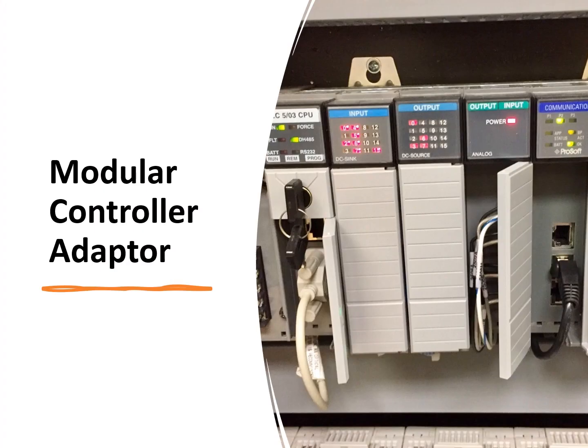Another modular adapter chassis shown in the figure below is the SLC 500 modular controller system. The configured controller system consists of the chassis itself, power supply, CPU module, SLC 503, an input module, an output module, an analog input-output module, and a communication module running Distributed Network Protocol 3, DNP3. The processor module,